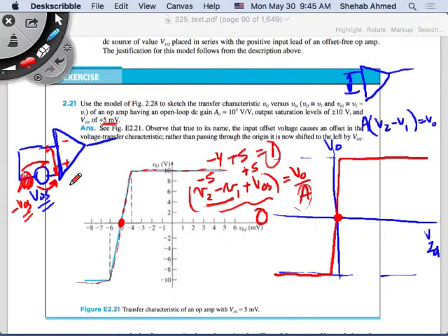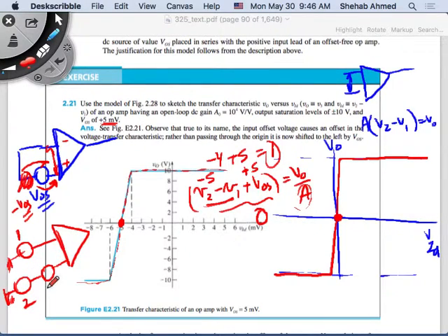If you're comparing two signals, one signal here and another signal here, but here you also have the offset voltage. So these are the two signals you're comparing with respect to ground, signal 1 and signal 2, right? This is V offset. You have to consider it. It's a voltage that is at the terminals of the ideal amplifier. So now you're not actually comparing V1 and V2. You're actually comparing V2 plus V offset minus V1, which is the equation that we have here. So if you're running this as a comparator, it will affect your result.